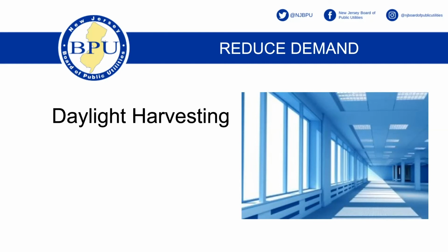And to do the daylighting, if this is a wall full of windows, and you have these 2x4 fluorescent or LED light fixtures, luminaires, all you need to control that is some sort of light sensor that's located over in this area that will sense the amount of daylight that's coming in, that will send a signal to a dimmer, and it'll dim. Maybe these circuits are separate. You probably have to separate those.